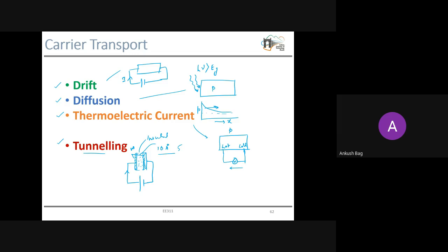In a capacitor, obviously there is no such limitation on the thickness. And if you can recall Maxwell's equation, there is a displacement current, because in a capacitor only AC current can flow, and that AC current is the displacement current, not the conduction current. So the actual carriers, the electrons, will not go through your insulator in the case of a capacitor.